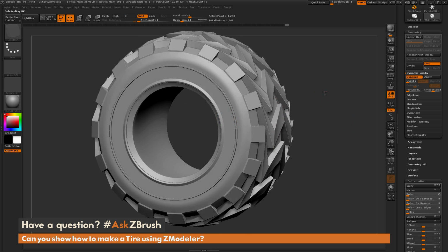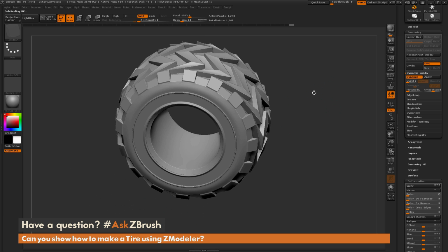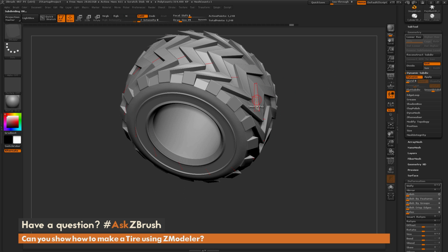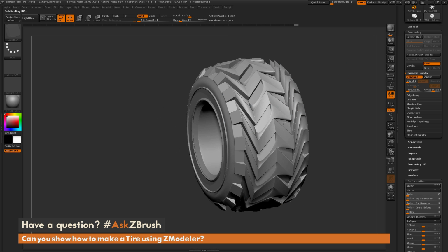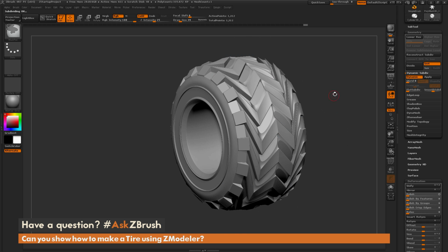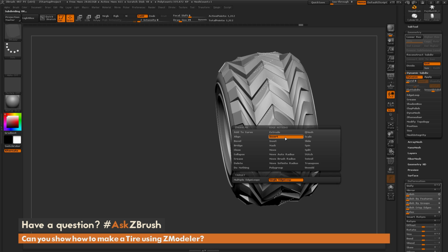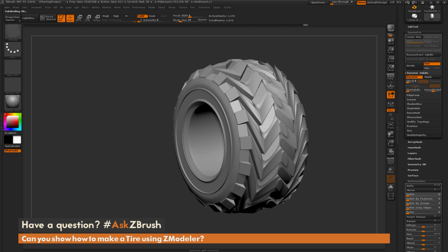Now, once you have this kind of set up too, at any time you can also come in and just modify this with the Q mesh action too. If I want to make round holes or maybe even start Q meshing this stuff here. And now I'm getting a little different kind of happy accident tire stuff going on here. Now I got some cool tread patterns like so. And bring these up and you come through and say insert some edge loops in here. And then even Q mesh some of these guys out.